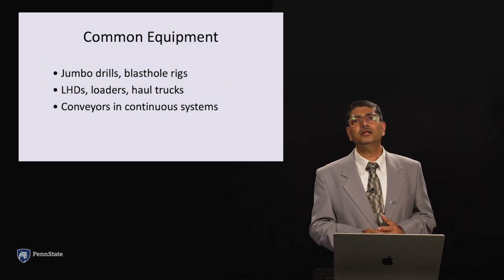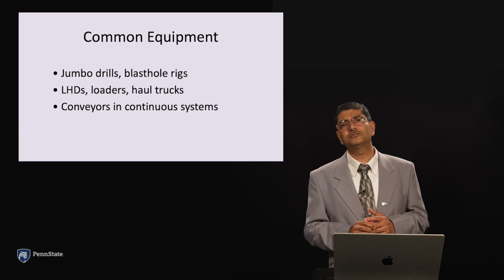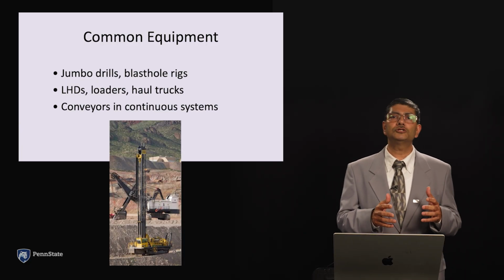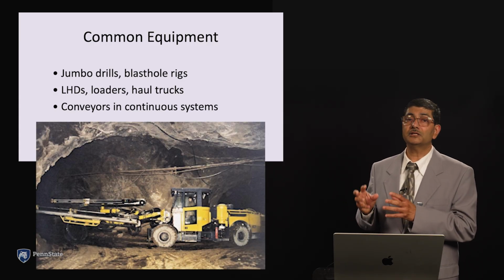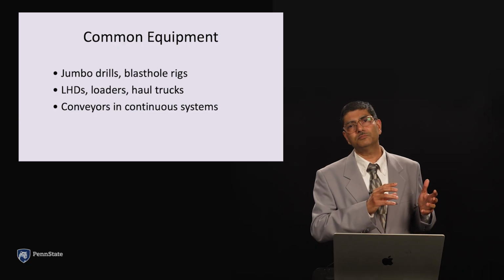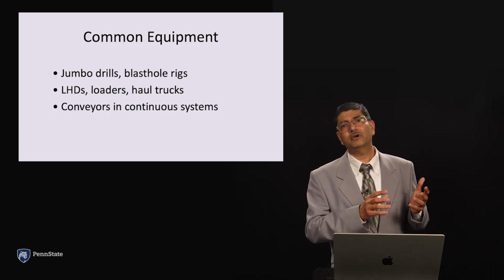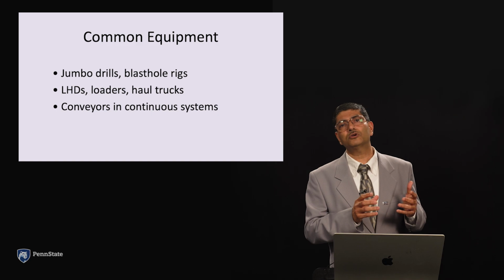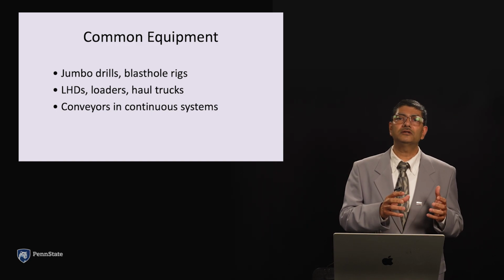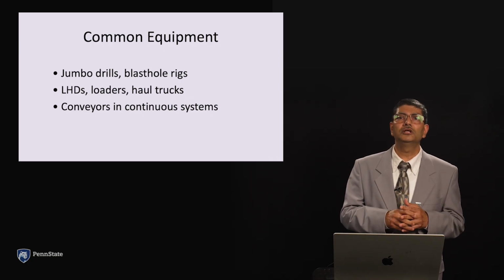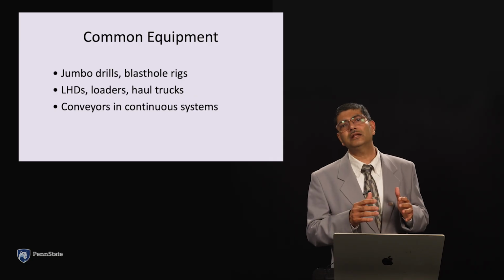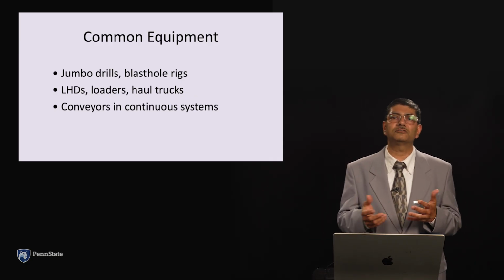Now drilling in hard rock context, and drilling is key for those unit operations. Holes are drilled to place explosives and sometimes of course for bolts too. The bit types vary. It can be the percussive bits, or for very hard rock, the rotary bits and the rotary percussions, and then for medium hard rocks, the rotary drag bits for soft rocks. Down the hole and the cable tools, those systems differ mainly regarding the energy transfers.